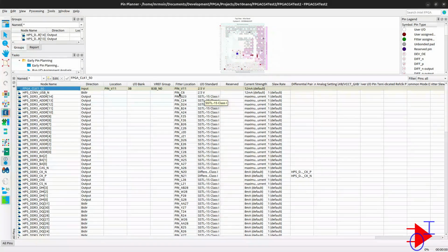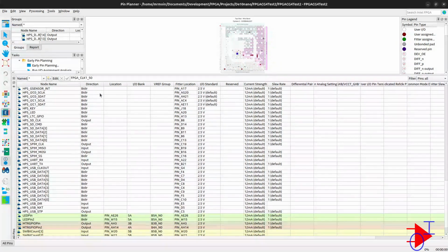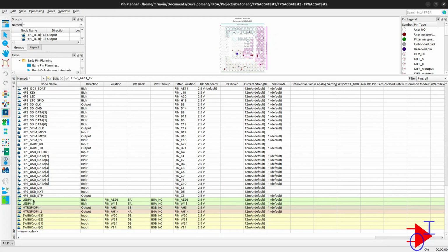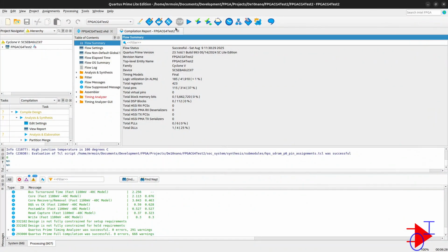And I believe there are 3 different connection pins that you can use for the 50 megahertz clock, and it depends which one you want to choose. And I've chosen the first one. Coming down here, as you know, we're using LED pins, then motor pins, and then switch connections, and that's it. So we have already connected those in the earlier attempts, so I'm going to leave it as is, and we ran the TCL scripts, and now we will execute the compiler one more time